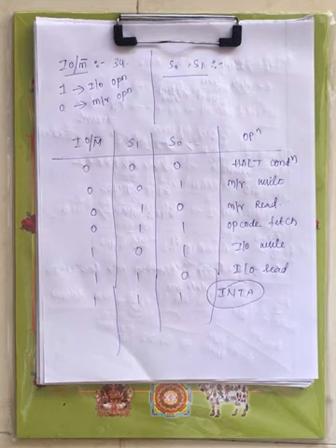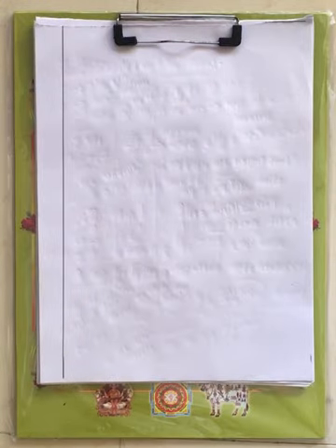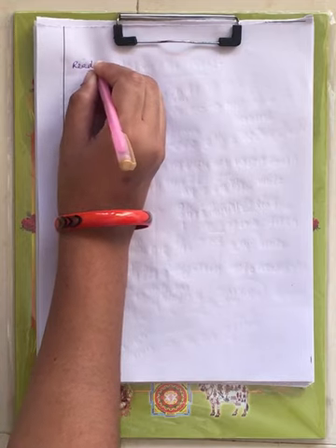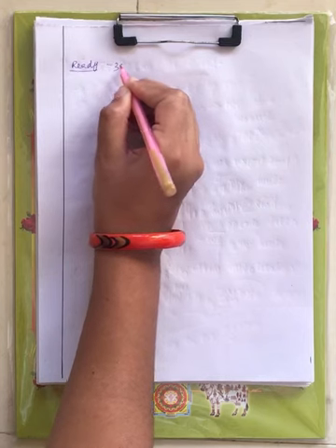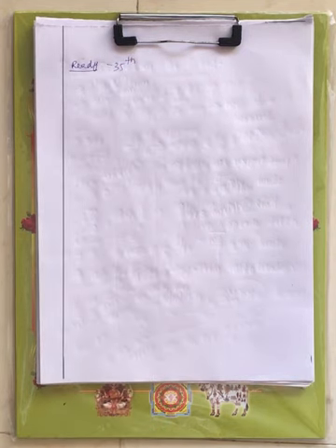Now coming to the next signal, ready. This is provided at the 35th pin. Next signal is the ready signal. This is used by the microprocessor to sense whether the output devices, that is, the peripherals, are ready for the data transfer or not.